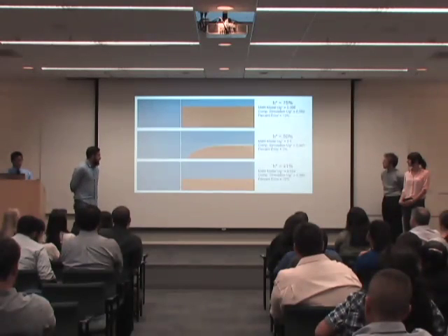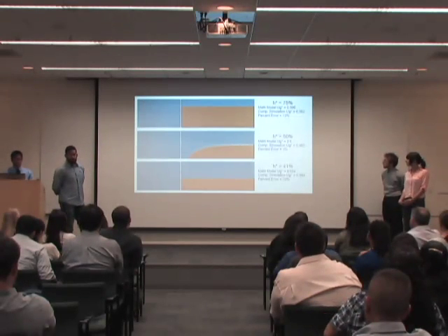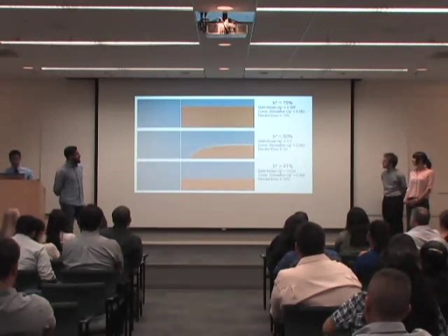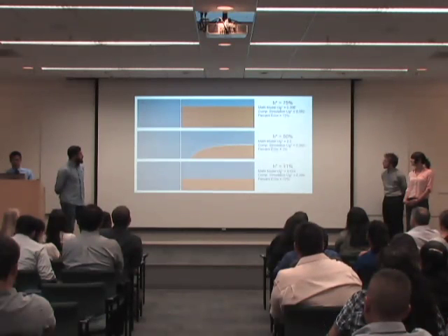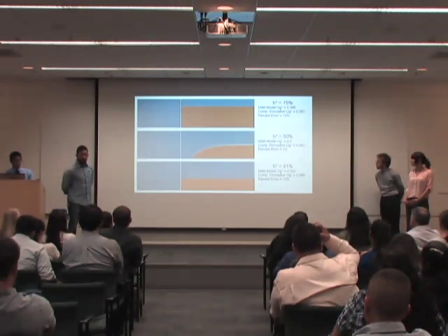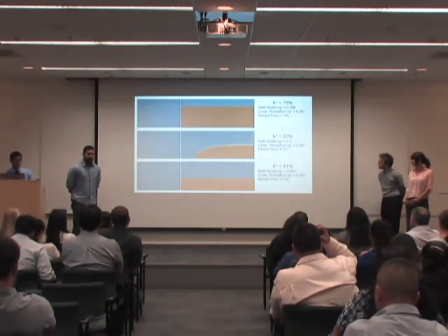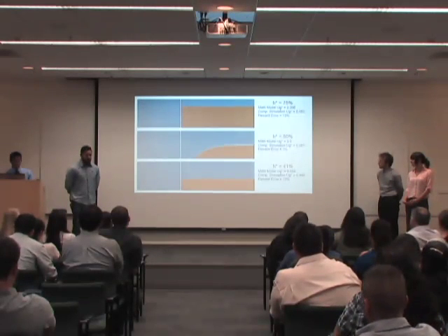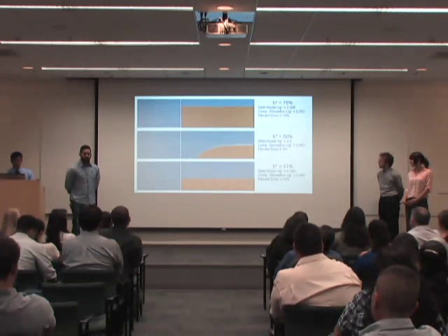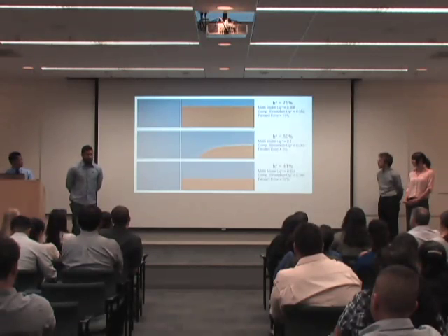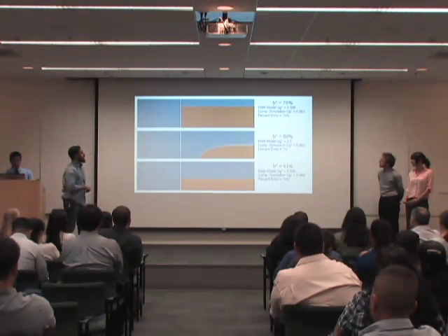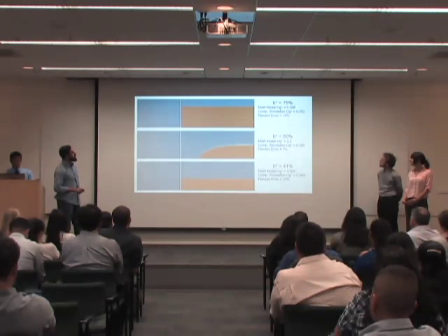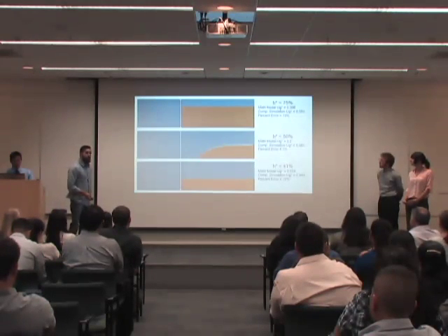At a height of 50%, the model is accurate, which corresponds to a head loss of 0. The simulation serves as an excellent benchmark when predicting a 0 head loss. However, it becomes problematic when our models begin to predict a head loss other than 0. For example, at a height of 75%, our head loss corresponds to a negative head loss, which means the energy is being gained.